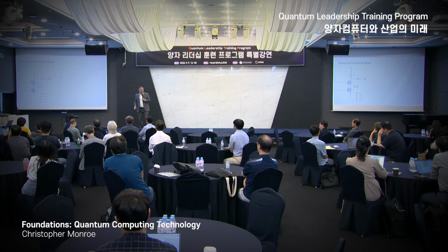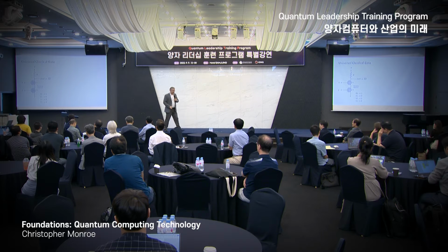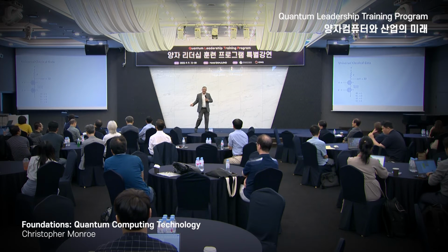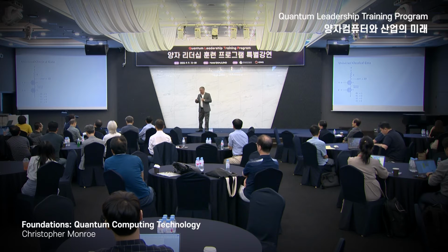It's a NAND gate, and you get that by simply stacking 2 transistors in a cascade like this, and you can clearly see that the output is the NAND of the 2 inputs, and you get this truth table. And that's universal. If you can apply NAND to any 2 bits in a classical machine, you can pretty much do everything. You can make adders, multipliers, and everything else you need.